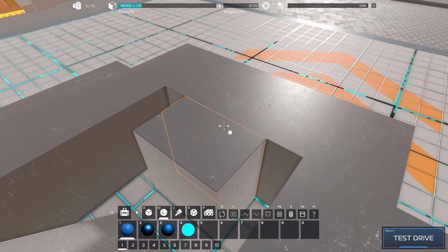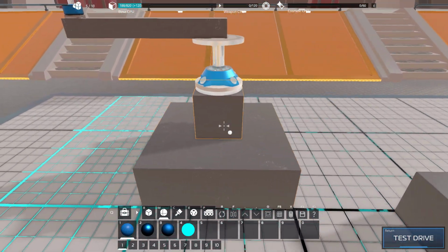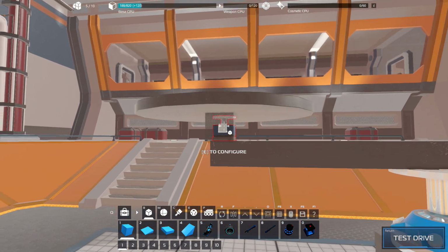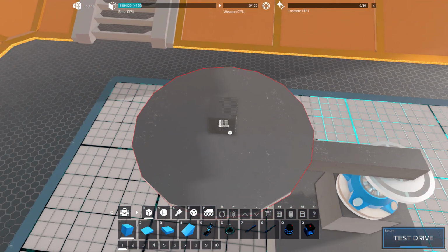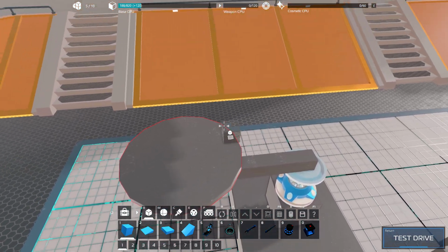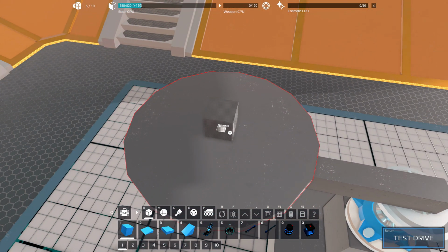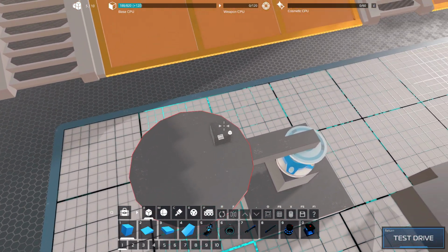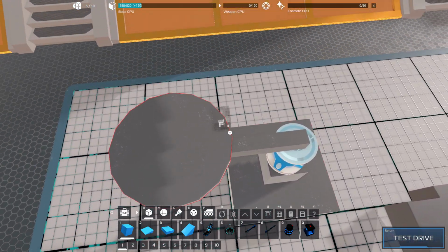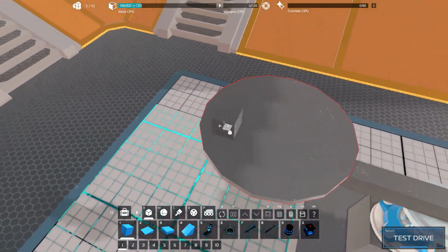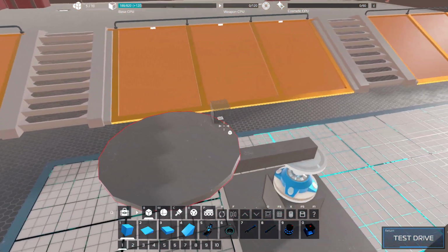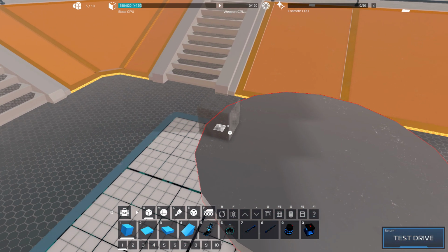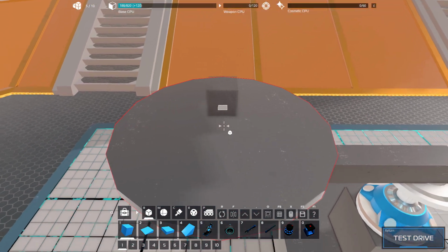So go to materials. If we do that, and then finally, this is a good old-fashioned gyroscope. It's just a plate, which, by the way, if you rotate an object, the amount of torque you'll get, or the resistance to it moving in this case, is going to be a function of the distance of the mass from the center. I won't get into it too much, but basically, the mass on the very outside of this plate is much more effective at preventing it from moving. It has a higher mass moment of inertia than material towards the inside.